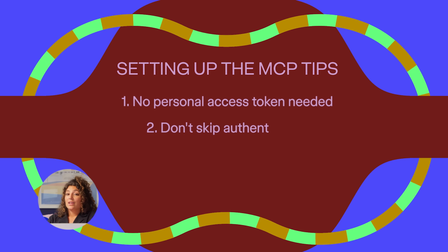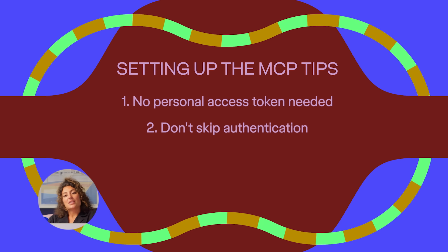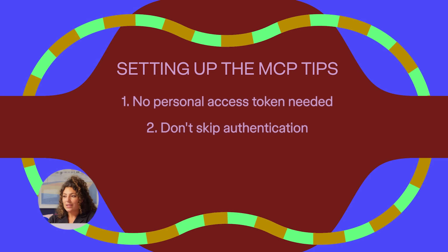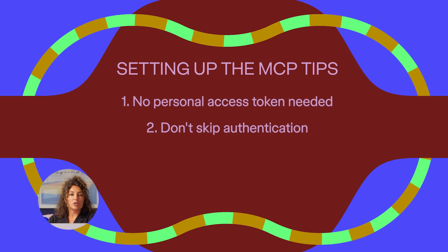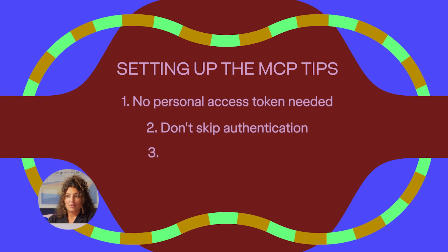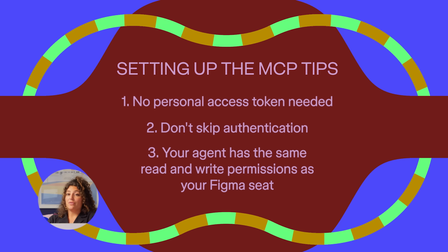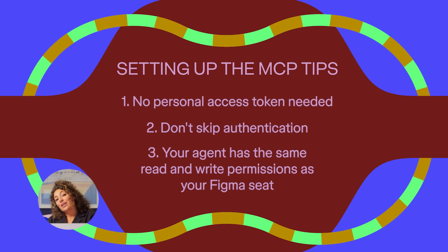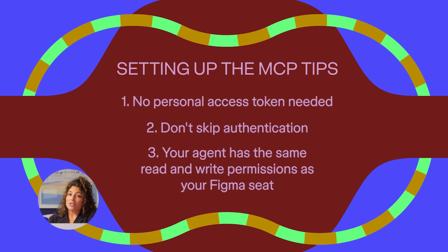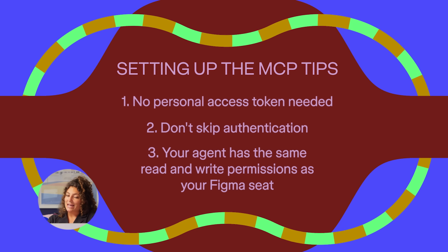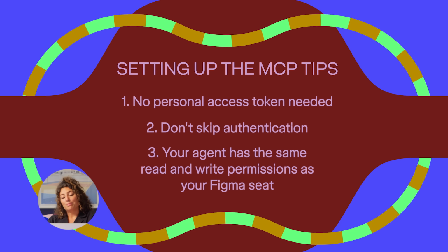2, if you installed but skipped the authentication step, the agent may fail silently or try to reinstall without prompting you to authenticate. These tools are imperfect, so make sure you not only install, but also authenticate. Do not skip this. And 3, once you're authenticated, the MCP follows your Figma permissions. If you can edit a file in Figma, your agent can too. If you have view-only access, the agent can read, but not write.